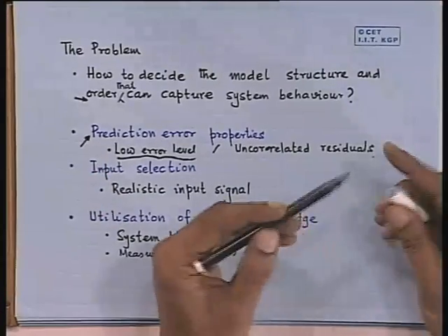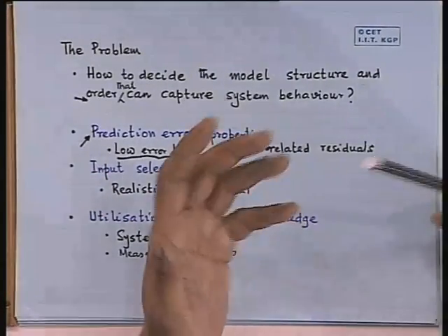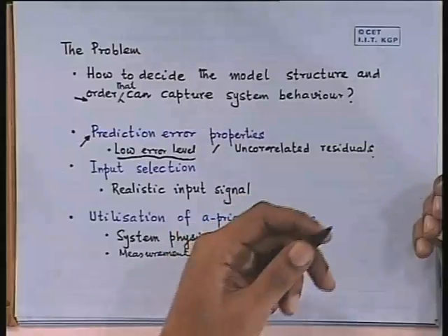Secondly, in some cases you will get some errors because you are trying to reject noise, so the model prediction and the measurement will be different. In fact, it is good to be different because you are trying to get the process variable before the measurement, so you are trying to reject the measurement noise.